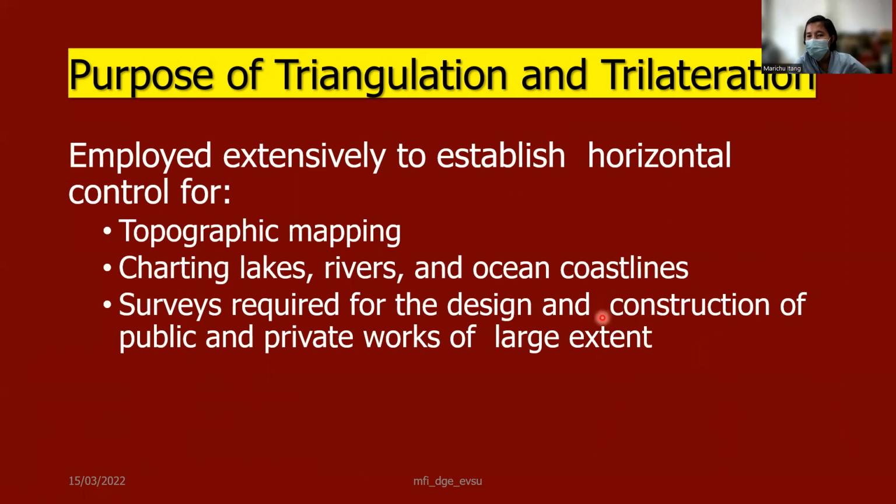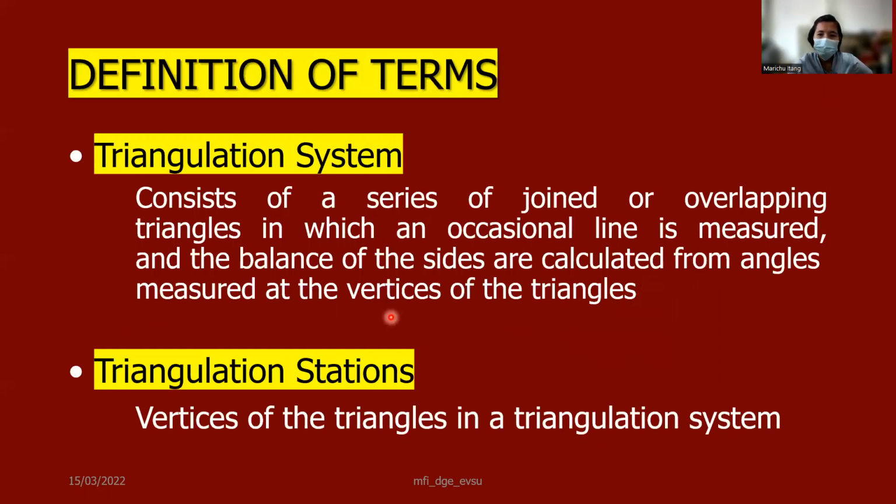Before we establish, we need to design, and after we design, we need to conduct an ocular inspection on the ground to see whether it is possible or impossible to occupy the points which were designed. There should also be certain computation and adjustment of our data before we exactly establish the monument or the control on the ground. So let's have some definition of terms.